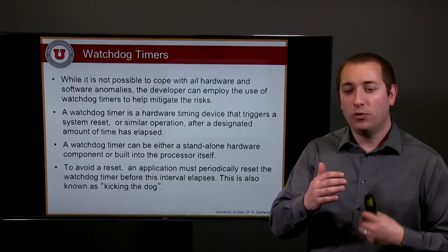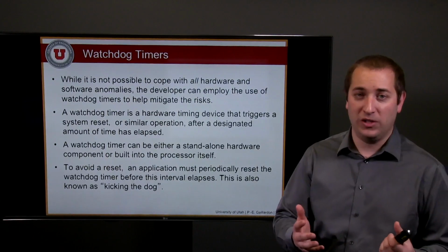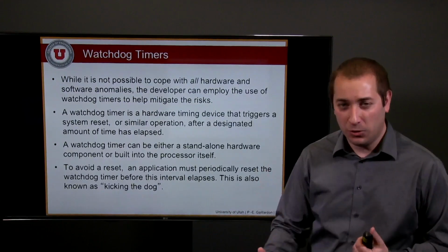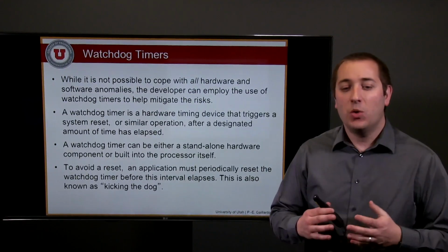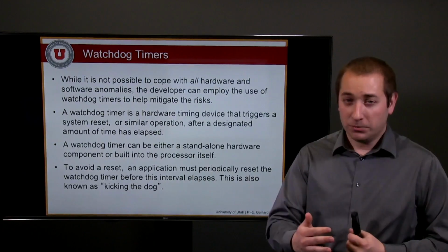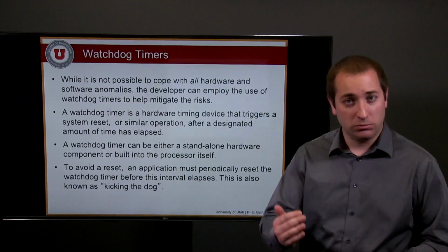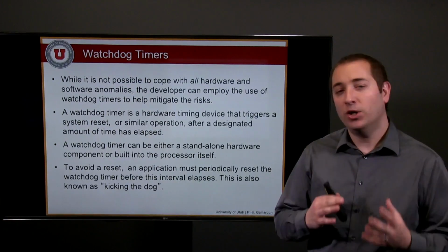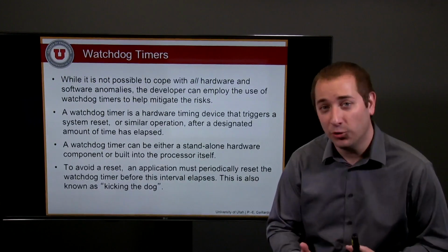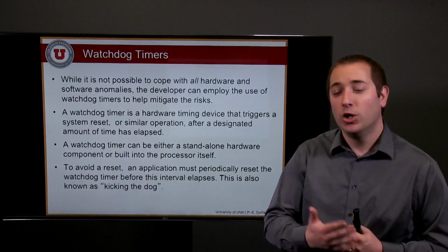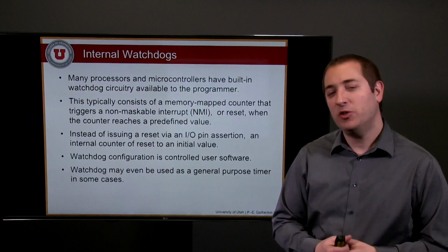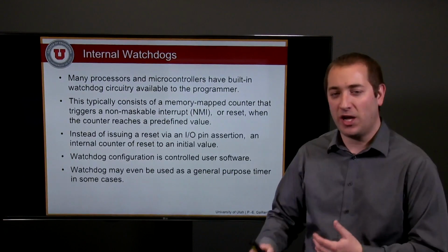A Watchdog timer is a hardware timing device, a regular counter basically, that once it overflows, will reset your device. So in order to avoid your device being reset, you want to regularly reset your timer to 0. The bottom line is that if the software has an anomaly and is stuck somewhere and is not able to reset this Watchdog timer, after a period of time you will end up resetting your entire system.